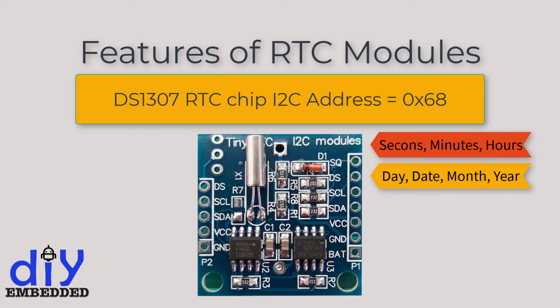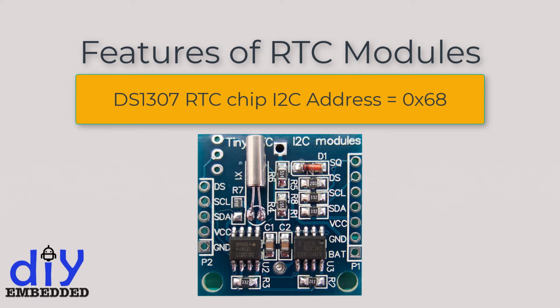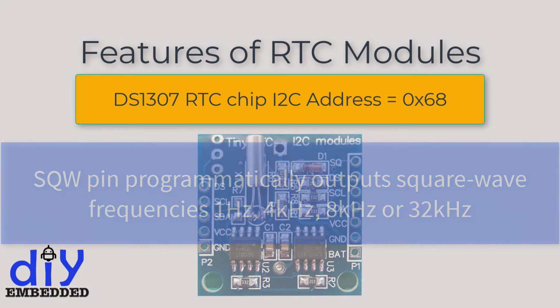The date at the end of the month is automatically adjusted for months with fewer than 31 days, including corrections for leap year. Valid up to 2100. The clock operates in either the 24-hour or 12-hour format, with an AM/PM indicator. The other cool feature of this board is the SQW pin, which outputs one of 4 square wave frequencies: 1 Hz, 4 kHz, 8 kHz or 32 kHz, and can be enabled programmatically.